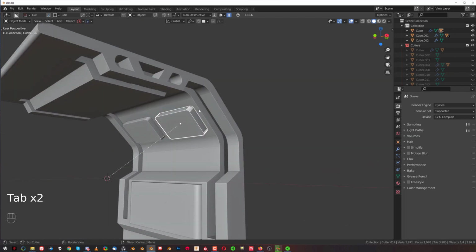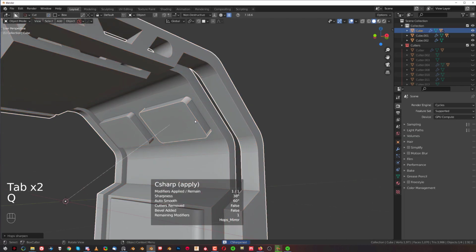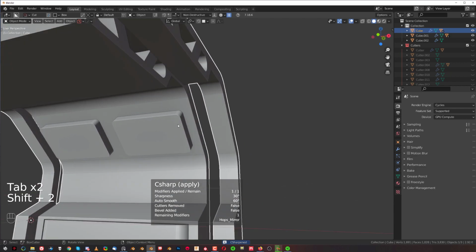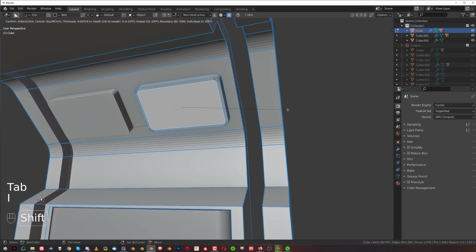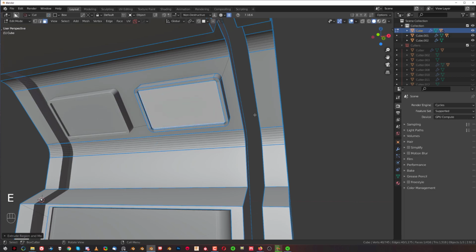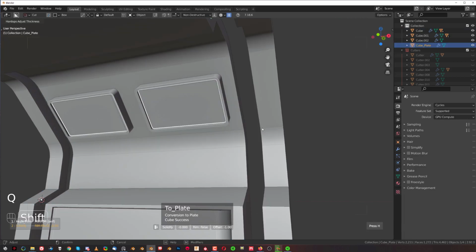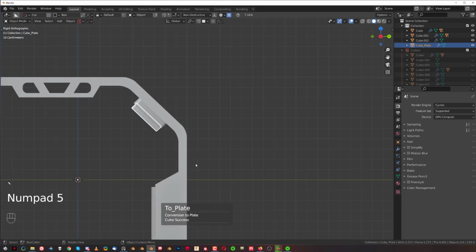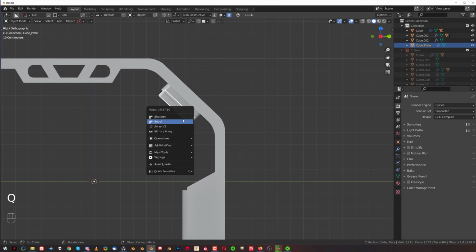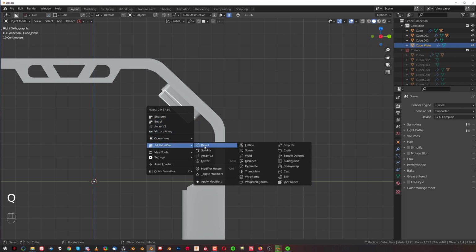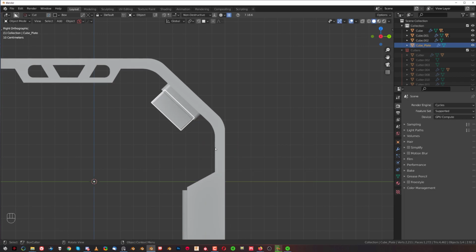And we can apply it now, right? And let's cut it inside of it. Let's just inset it and extrude it, and we're going to shift curve extrude this, all right, like that. In fact, we're gonna solidify it a bit further. So go to modifiers. Where are they? Where are the modifiers? Here. Solidify it outside like that.